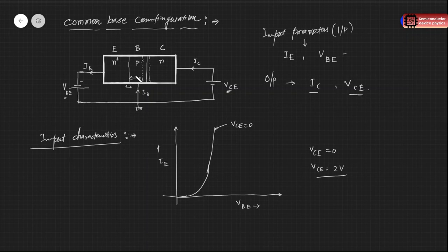Then in the base region, the carrier concentration will increase, because we are injecting electrons from the emitter into the base. Now the base width is less, so the electrons will be crowded in the base. So the overall electron concentration gradient in the base will increase. So there is some effect on the emitter current. In that case, the emitter current will increase, because there is a larger concentration gradient in the base as the neutral base region is now narrower.